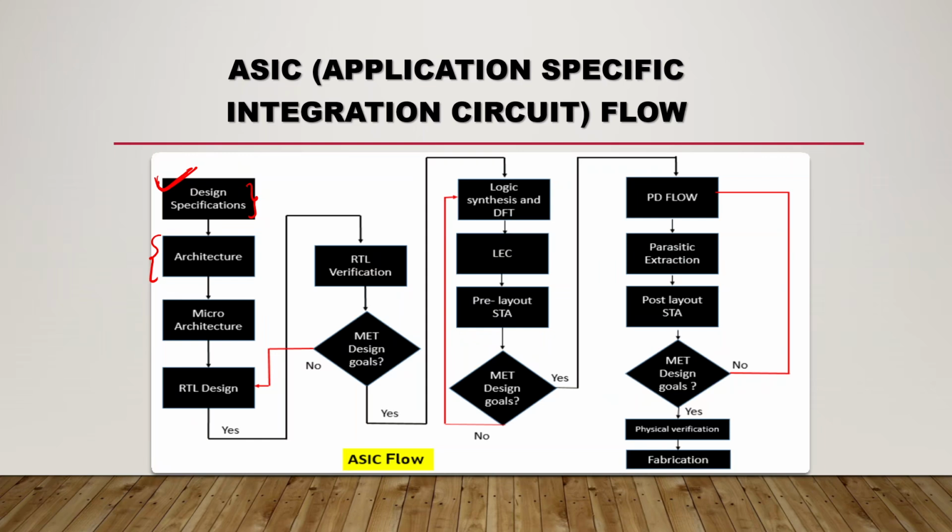So arithmetic and logic unit means, for addition, we need some 4-bit parallel adders. For subtraction also 4-bit parallel adders are required, and for multipliers full adders are required. And next, for logical operations we need AND gate, OR gate, XOR gate, XNOR gate, NOT gate, buffer gate. So he is telling that he wants to design a 4-bit ALU, and from this I will decide how many modules are required.